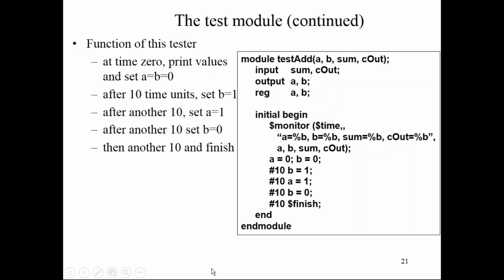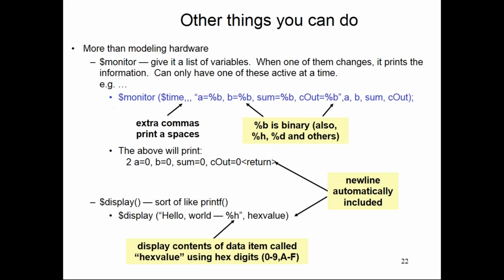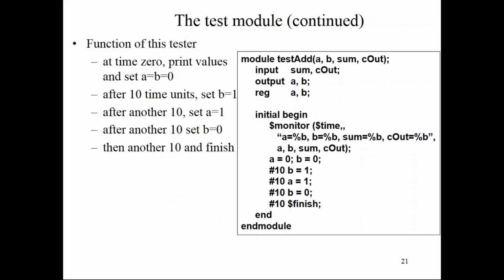Here for this program, your delay will be 10 nanosecond, but in my program I gave 200 nanosecond delay. So based on the delay time, your output response also changes. If I use the $finish statement, that means the simulation will terminate after the particular time period.